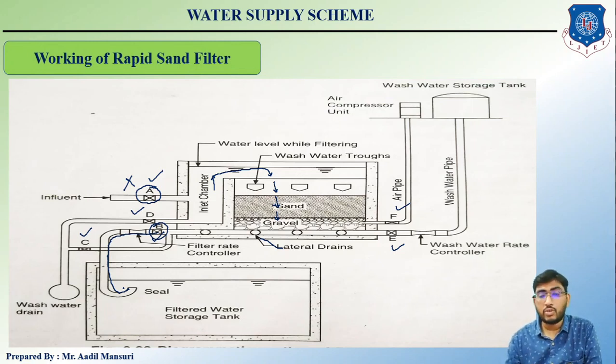and after stopping, we will close valve A and close valve B. Right now all the valves are closed. Fine. Whatever water is there, what we will do next is open valve F for allowing compressed air, supplied at 1.25 to 1.5 meter cube per minute per meter square of area for 4 to 5 minutes.